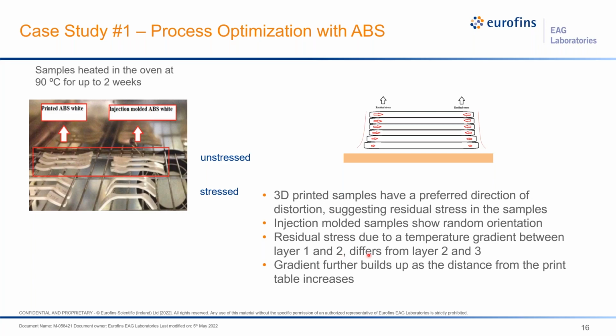And the stresses come from the fact that there is a temperature gradient as we're doing the print. So this is really hot and this cools down. And so we have residual stress built up at the top of the part. When we're heating it, we're relieving the stress.